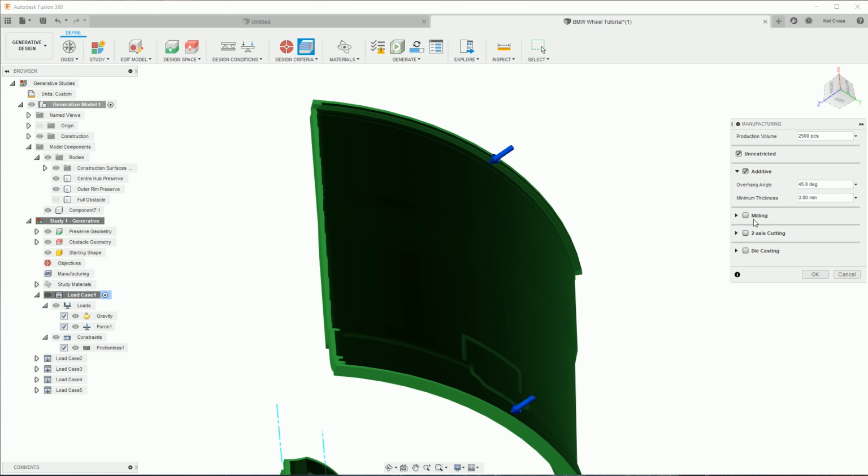But I'm going to untick milling because in my testing, I found that the milling and cutting options gave very unpredictable, unusable outcomes for this load case. So we're going to go for unrestricted. We'll click additive as well and die casting. So for die casting, we're going to untick Y and Z. So the ejection direction is X. And then I think that should be all we need.